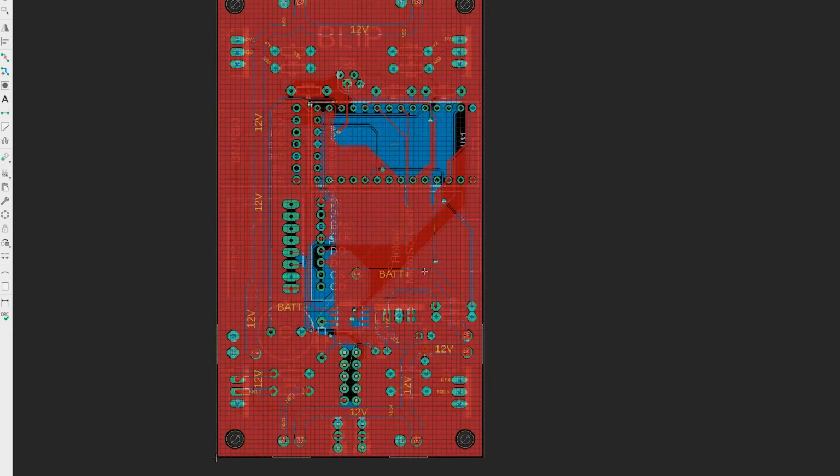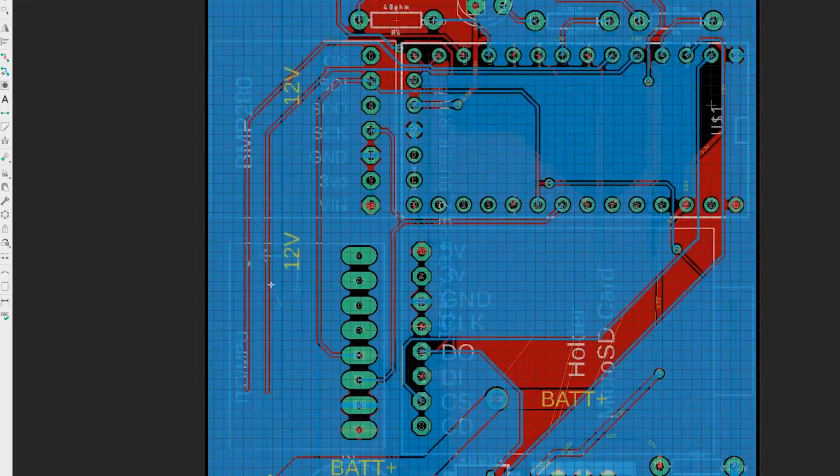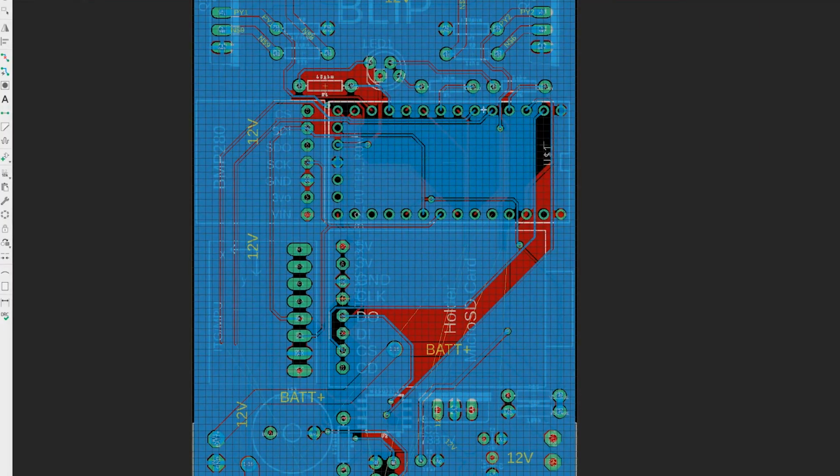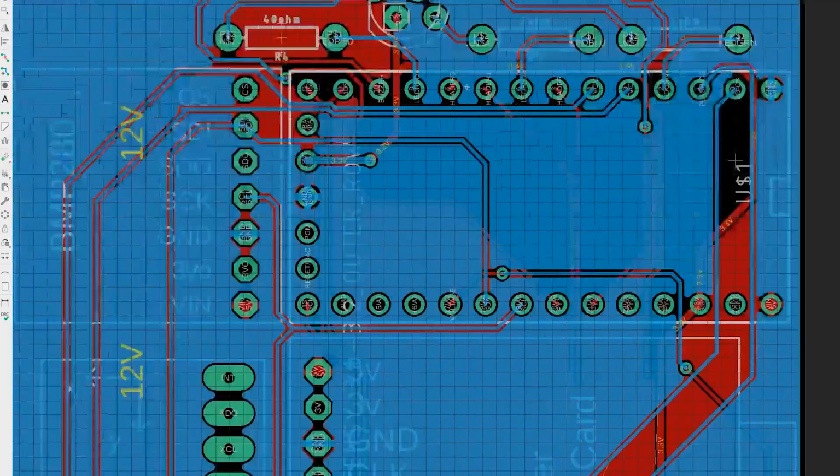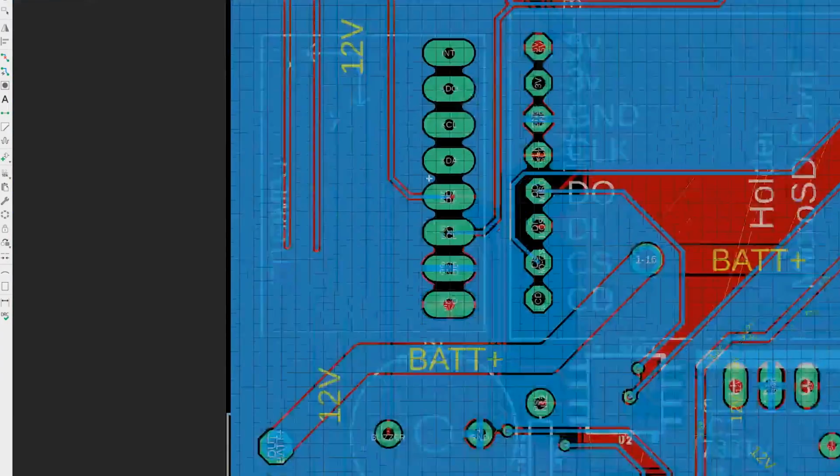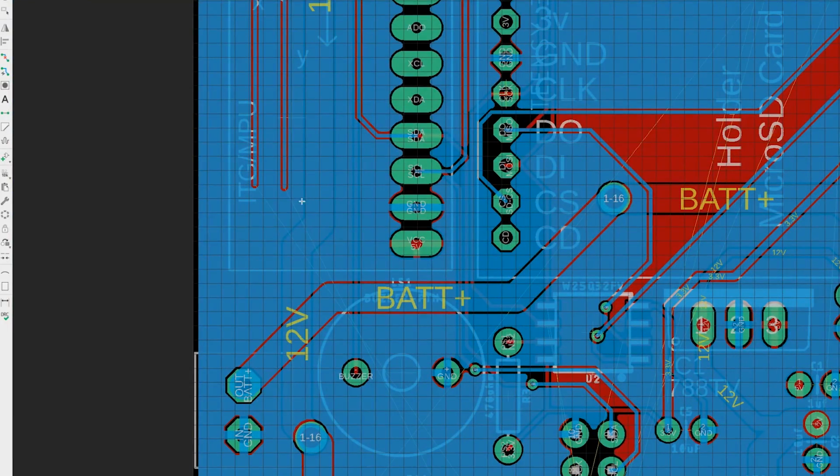And I think maybe the best way to do this is to just finish it out. So I'll show you where I left off. We'll switch to the bottom layer of the board now. The thrust vector control, this is maybe a good example here. So the thrust vector control servo lines, they go down on the left side of the board here, and they're not connected yet. This is something that I end up doing with a lot of the printed circuit boards that I design. As I'm designing, I just try to move all of the signals down.